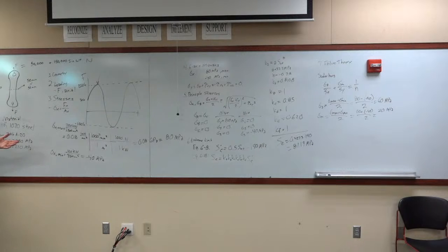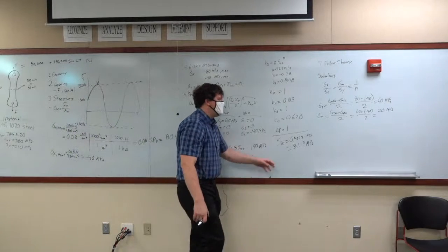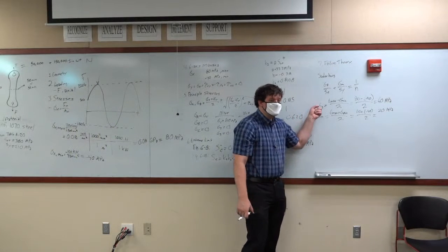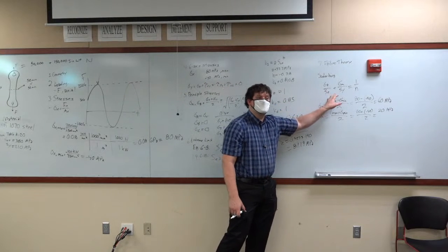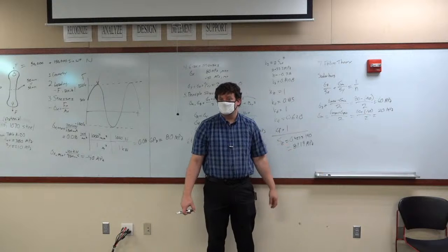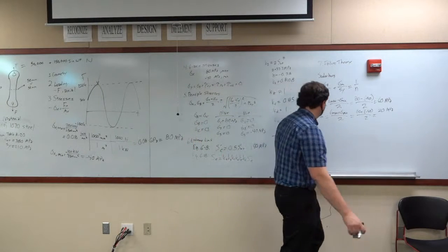That's great. So it is your sigma A value that tends to be the most critical, and the reason for that is because your SE value is so much smaller than your SY. That is the fundamentals of why we're talking about fatigue here.